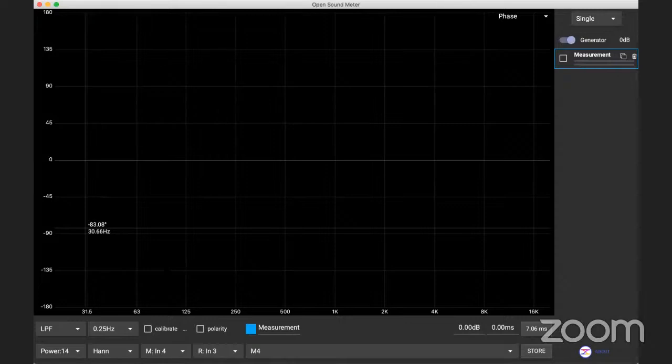This is not through the mic. I'm just showing you an example right now, which is why I changed the inputs. I have 2 separate auxiliary sends, aux number 3 and aux number 4 from the console. Aux number 3 is my reference, and aux number 4 is the signal I'm going to measure. I'm going to measure the phase of aux number 4 compared to aux number 3 internally. Do you understand? Yes or no?